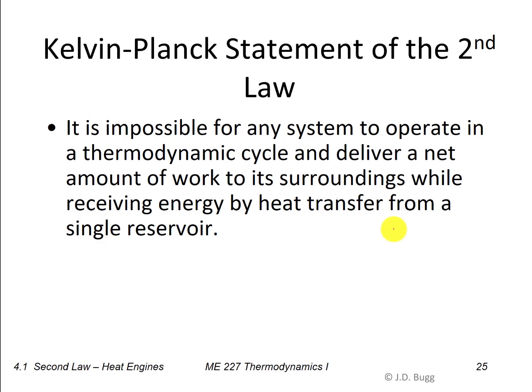So now let's take a look at a formal statement of Kelvin-Planck. It states, it is impossible for any system to operate in a thermodynamic cycle and deliver a net amount of work to its surroundings while receiving energy by heat transfer from a single reservoir. If you'll notice, this is describing the scenario that we set out to do. We had a single reservoir and we were drawing heat from it and delivering work to the surroundings. So that is not possible.